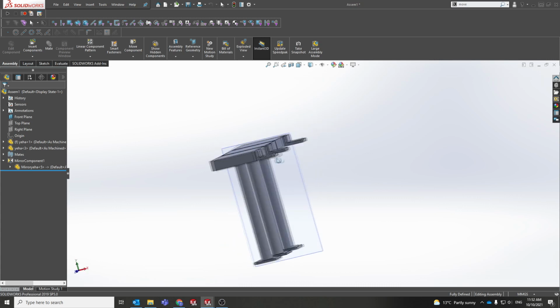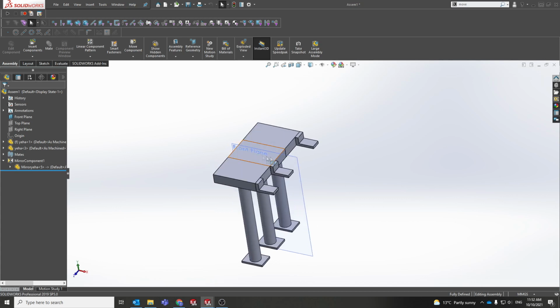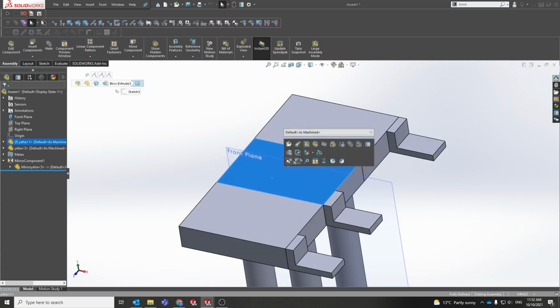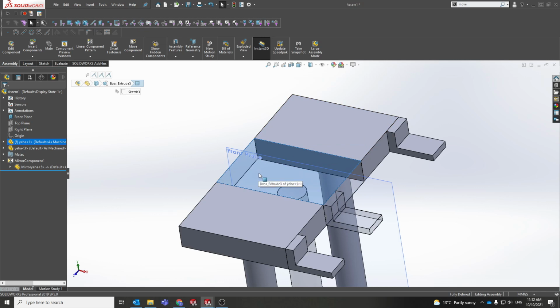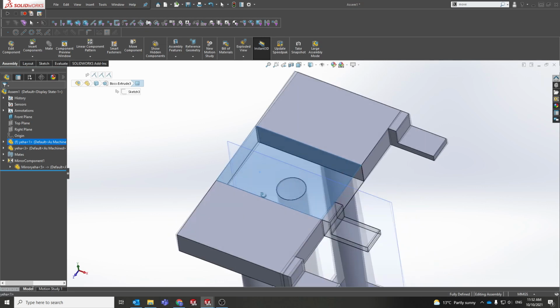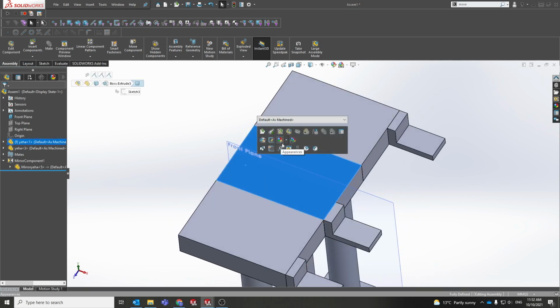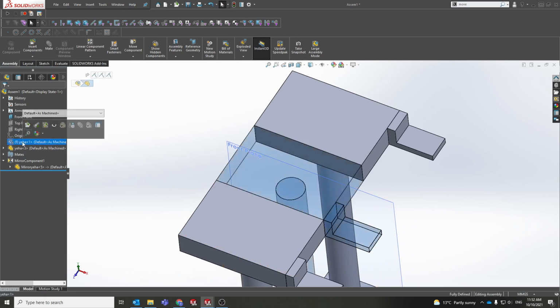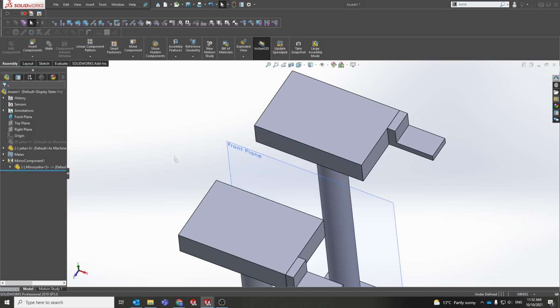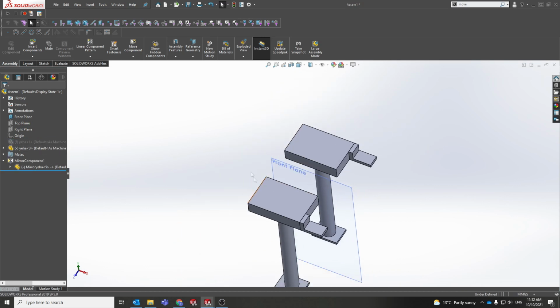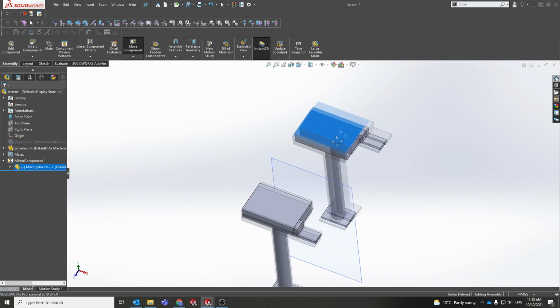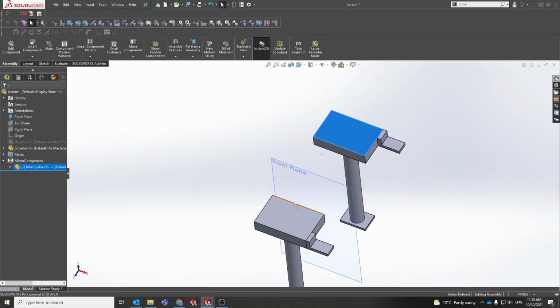Now, if you're in here, editing your parts, you can do it in here in the assembly view. So if I click on here, so I'm just left clicking, and then it comes up with a bunch of options. Let's say if I want to change the transparency, so I can actually see through some stuff. Or I can hide that part. There's also suppress as well. So instead of hiding it, it's actually not in the model anymore. But if I wanted it to be there with its previous constraints and whatnot, so at the moment these aren't constrained to anything now, right?